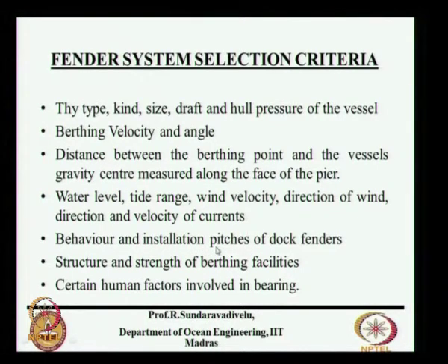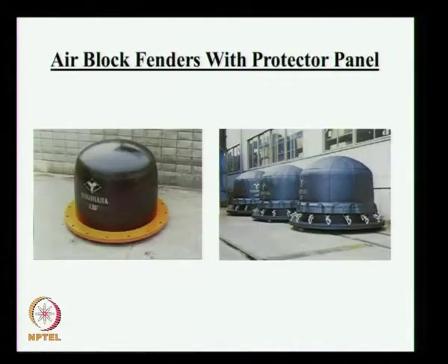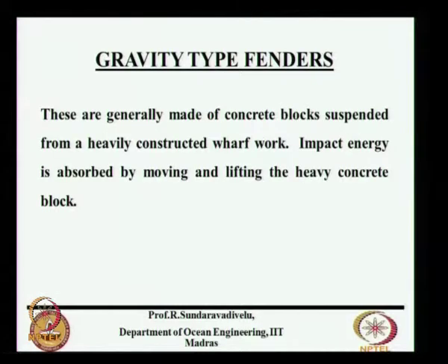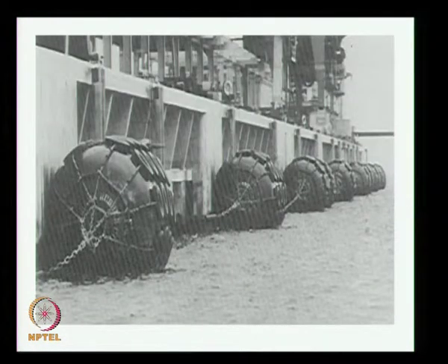This interval is typically 0.1 times the length of the vessel. Suppose you have a fender like this placed, installation pitch means the center to center of the two fenders. This distance is typically about 10% of the length of the vessel. Suppose the length of the vessel is 250 meters, then this distance is about 25 meters.